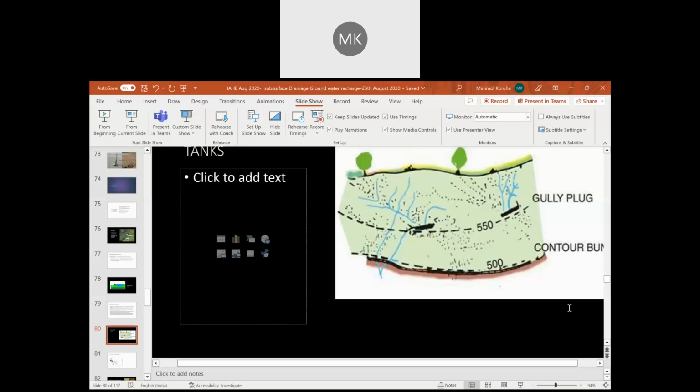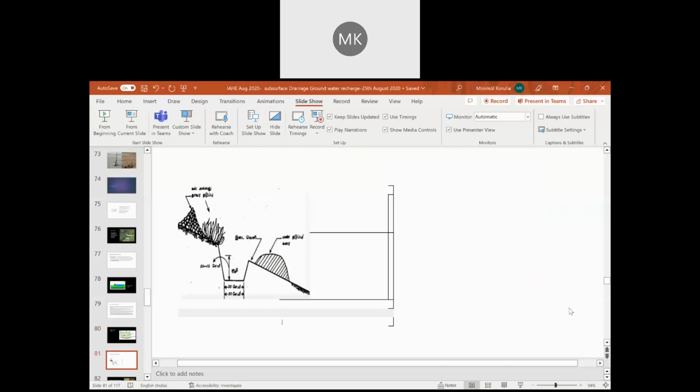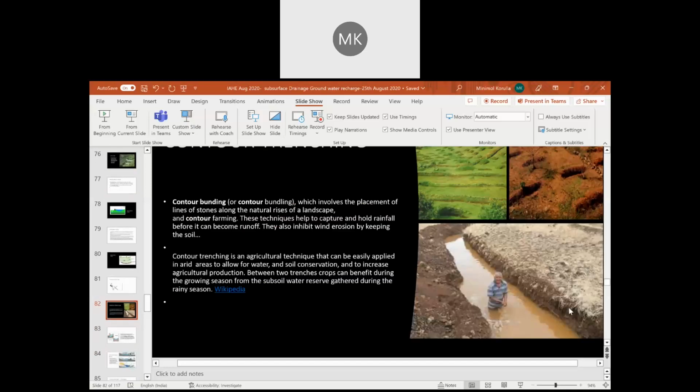Gabions are just rectangular baskets filled with stones, and the upper portion is again a reinforced soil structure with a green fascia, okay. And between the backfill as well as the structural fill, there will be a chimney drain, okay. So this chimney drain can be an aggregate drain, or it can be a drainage composite, okay.